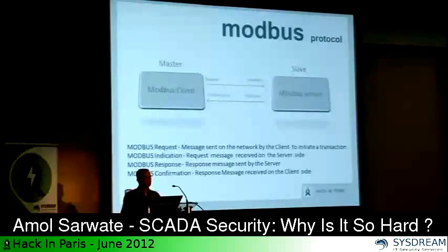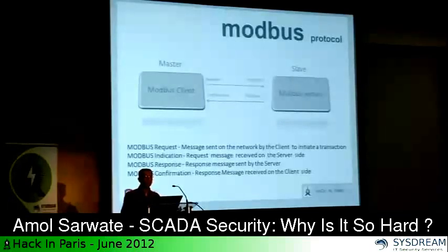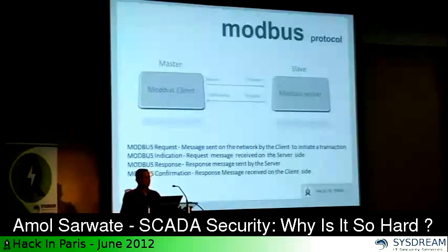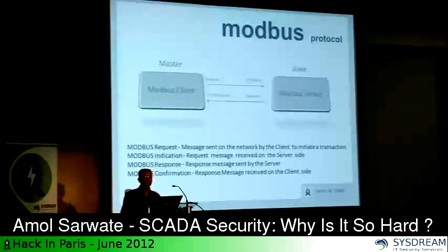Modbus is a pretty old protocol, about 35 years old. It's a pretty simple client-server protocol. If you know any other client-server protocols like FTP, HTTP, Telnet, SSH, the basics are the same: the Modbus client sends a request to the Modbus server, and the Modbus server gives back the response. The only difference is that the client in this case is called the master and the server is called the slave.